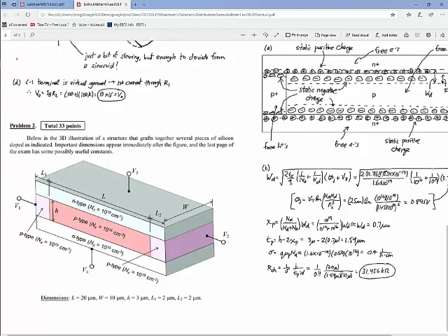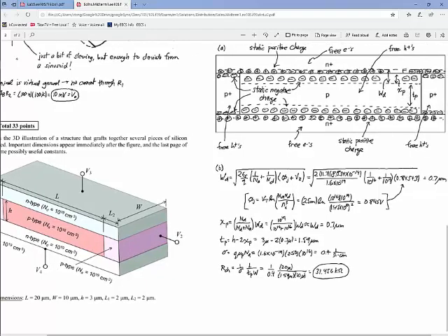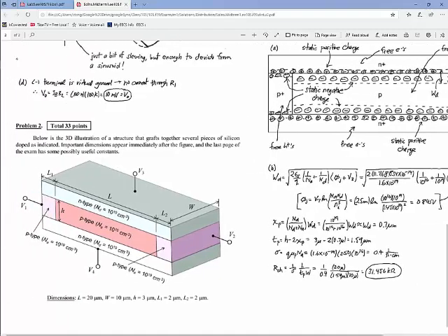What this really is actually is a transistor type thing. But it's a transistor that's very different from an MOS transistor. So what it is, these junctions out here are P plus junctions, like you're seeing even in the cross section right here. And so when I put a terminal here and I put a terminal here, I can send current through the P-type region. But I can actually control how much current can go through by changing the voltage up here and there, because that will make the depletion regions get bigger. And I actually can make the depletion regions get so big that they cut off this channel, and so the thing doesn't conduct. So I can turn off this thing by putting a large enough voltage on these terminals here because you're creating that depletion region.